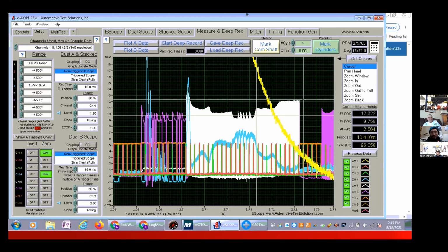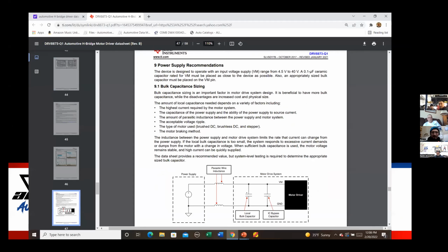Okay. Well, right. But so in this case right here, having the data sheet, finding the data sheet, looking at the fault recognition and the fault response shows you that driver, everything involved, the logic, the driver, the whole thing is doing exactly what it's supposed to do. Right. When it did it, for the time it's supposed to do it, everything. And that should be a clue that not only is the driver and the logic doing its job, you don't want to even think about replacing it yet, because you might put in a broken freaking part and really put you into the tailspin, the rabbit hole that we find ourselves in.